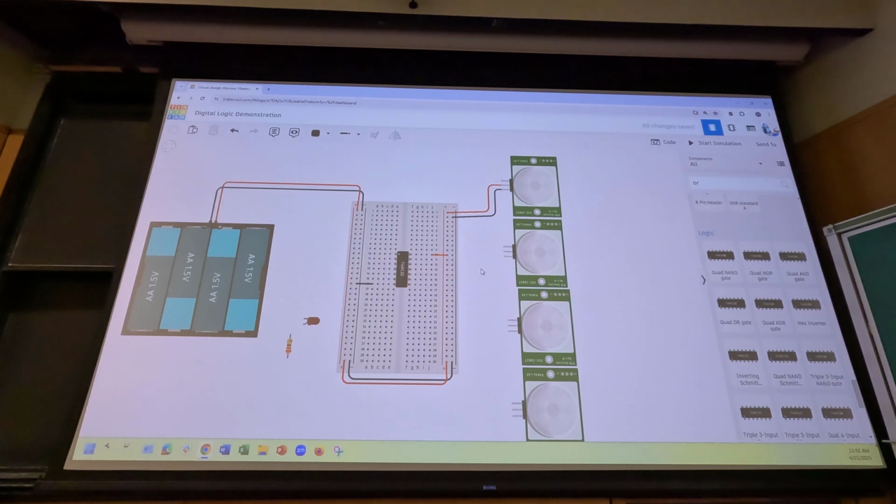If you have an OR gate output wired to a sensor output, that might be what's causing the short, because they're both trying to act like an output to the other. But maybe that's not how you had it wired, but that's one reason I think could blow it up. If the output of the OR gate tries to go low and the sensor detects motion and tries to go high, then that's creating a short between high and low. So double check your inputs and outputs.